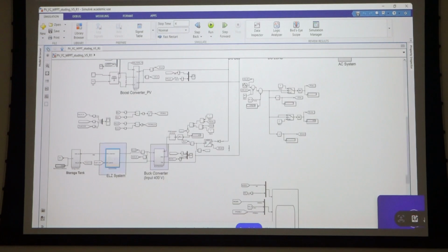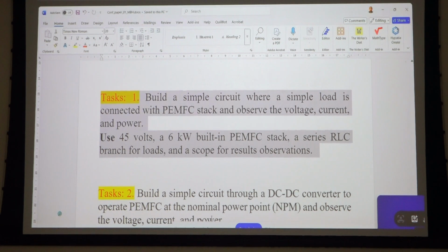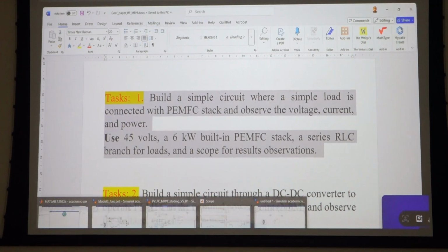The other way is using Simulink, where there is a user defined function, which you use as a mathematical equation to model it. You mean in Simulink or in the M file? M file and Simulink are both linked. You can link both, but you can also do it separately. Only an M file is also possible, without using any block, just MATLAB coding. But when I use both, then what should the power GUI be? What should we use, whether it is continuous or phasor?